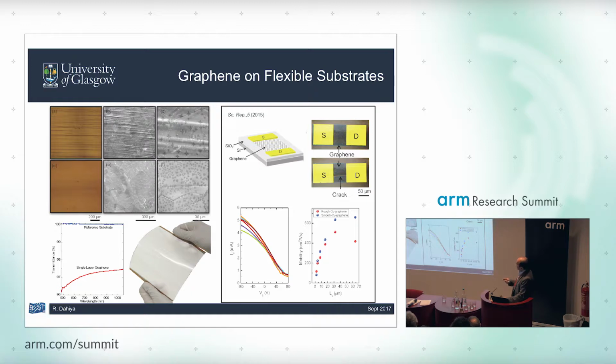We did it on a highly polished copper, not the commercial highly polished copper. This is the commercial one. We just took copper which is used in lithium-ion batteries. Because of chemical reaction, it is much smoother than what you get highly polished. So when you go to nanoscale, even highly polished copper will have these lines that you see here. Because graphene is a single atomic layer, when you transfer this graphene onto a flexible substrate, these lines become cracks. So there is no conformal contact between the two surfaces. Whereas in this case, we noticed that there was no crack.